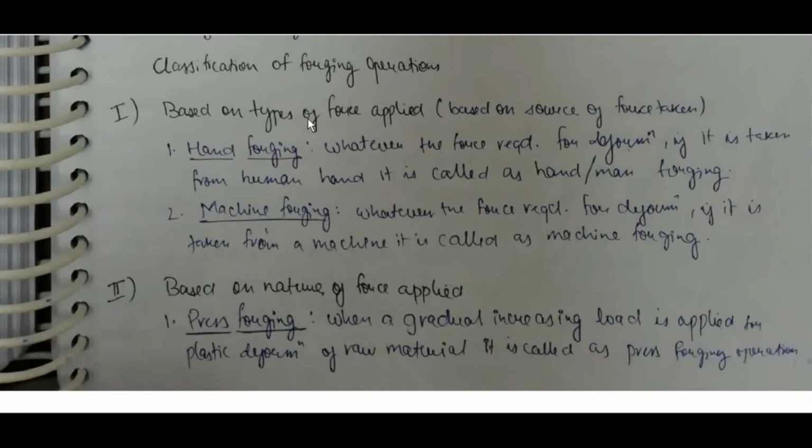Initially, the material tries to expand but is resisted by friction generated by the stationary die surface, but only at the end of the raw material, whereas away from the end there is no frictional resistance.